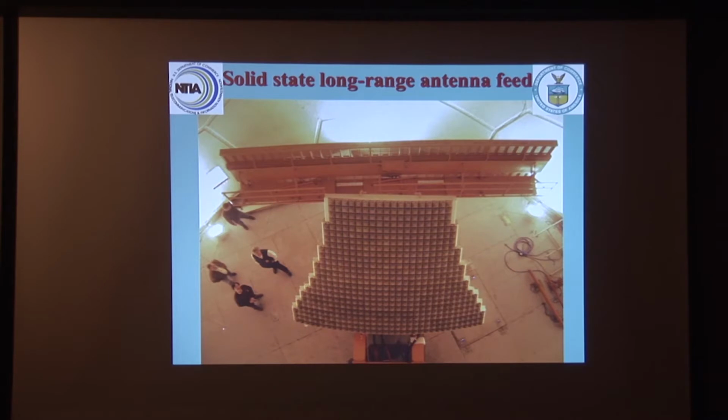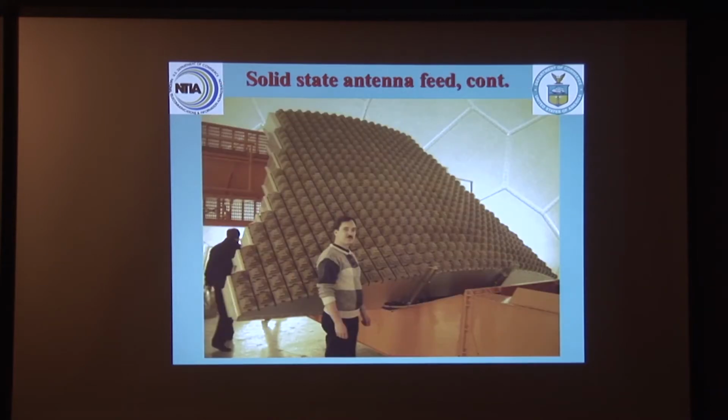And the peak power level is still 1/10 of what a tube would produce. So what they've done, in effect, is build the transmitter with all these modules right out here on the feed in front of the radar reflector. Again, when they get the echoes back, it operates reciprocally. And here, to save space, they've actually put the beacon antenna in front of the feed, like so, instead of putting it up on top of the main reflector. So there's another view of the solid state feed.